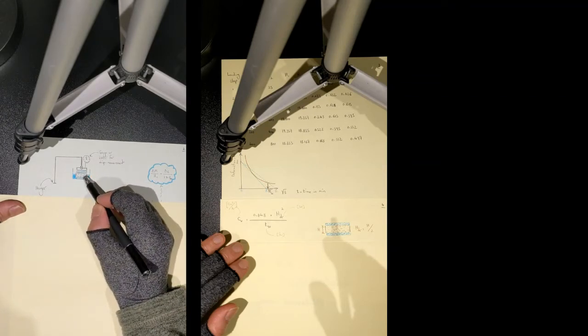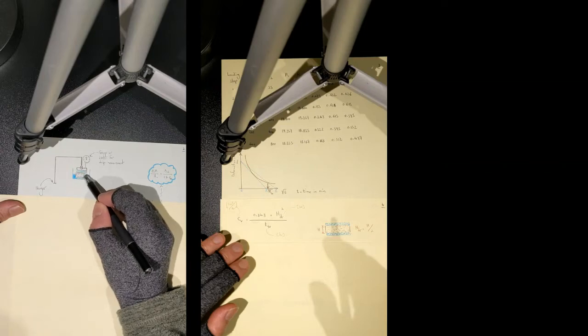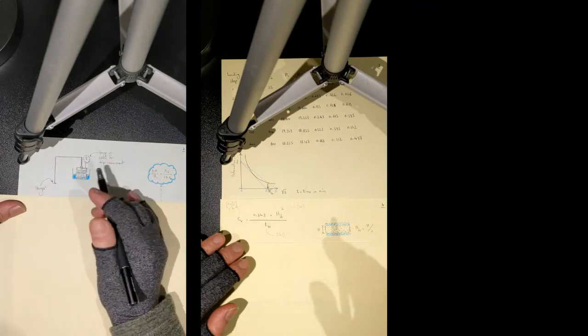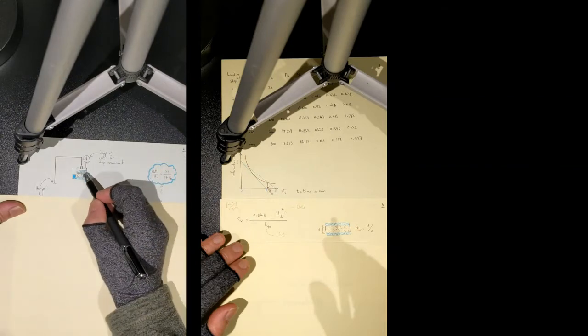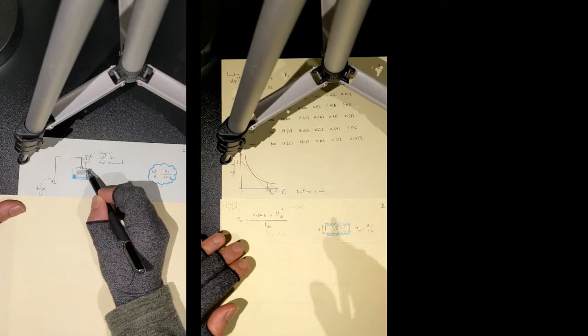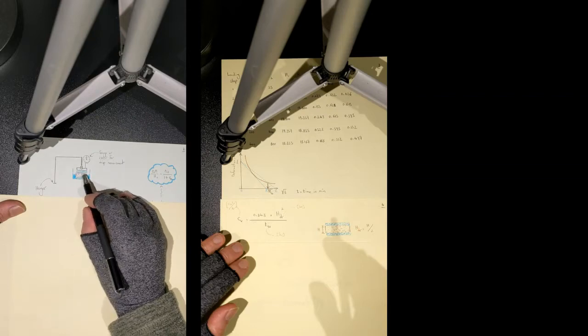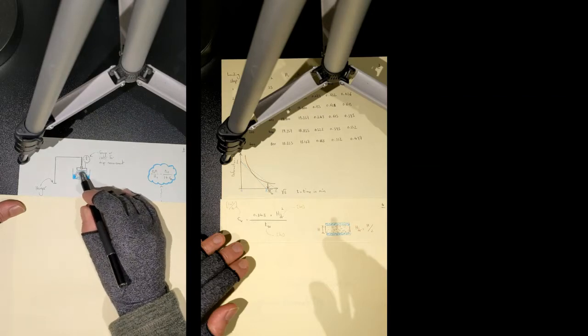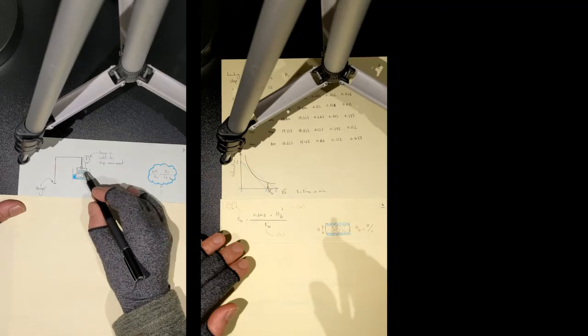You can see these red lines. By the way, this is a cross-sectional diagram. The red lines represent filter paper. Now you use these filter papers, which are essentially papers, to make sure that when water is moving in and out of the soil specimen, the fines, the clay and silts, small particles are not migrating out or in. So it's kind of, as the name suggests, a filter. And you can see that you've got this filter in between your soil and something which kind of looks like bubbles in blue. And these are your porous discs.